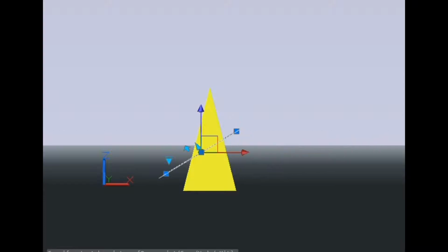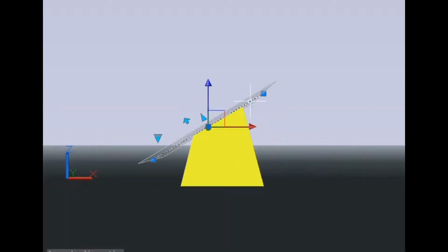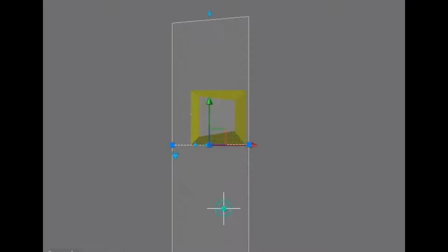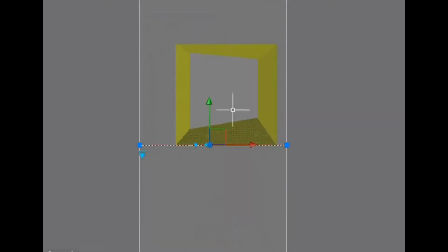Now you can see easily when I cut the solid with an inclined cutting plane, the square pyramid will look something like this from the front, and from the top it will look something like this. The square base will be visible, but at the center you will find some trapezium like portion, trapezoid. This is going to be a final front view and top view.